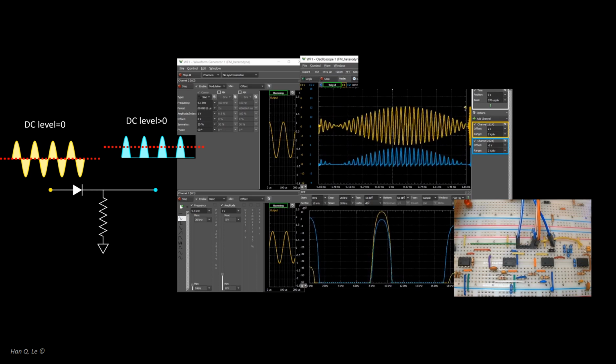Here, the blue trace shows that the diode output has only the positive component of the input, minus the contact potential of approximately 0.6 volt. Although this reduction of the signal by the contact potential is a slight disadvantage, as long as the signal is in the level substantially above 1 volt, this approach serves the purpose of demodulation application with the advantage of simplicity, using what is available in the electronic kit.